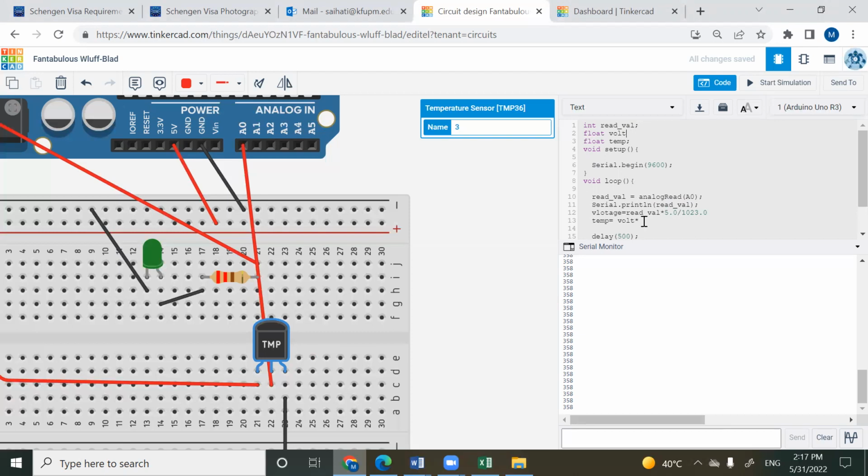What is this conversion factor? What I have now is a value that has been converted to volt. If I want to convert this to degrees centigrade, what should I do? I should multiply it by a factor that has degrees centigrade divided by volt, right? Do you agree? Yes. So where should I get that factor?